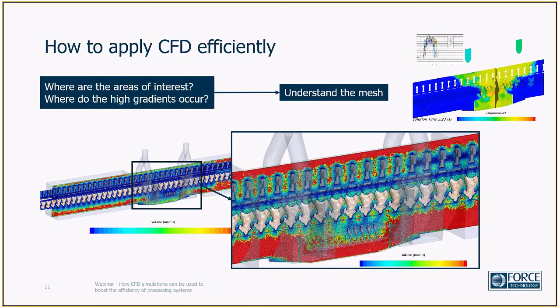And if you are not very familiar with CFD, then you can also think, but then I can just refine the entire volume as much as I can, and then I avoid the problem of the accuracy. But then that would be extremely time consuming to run a CFD simulation. So again, the key is a compromise between cell size, or the accuracy of the results, and simulation time.